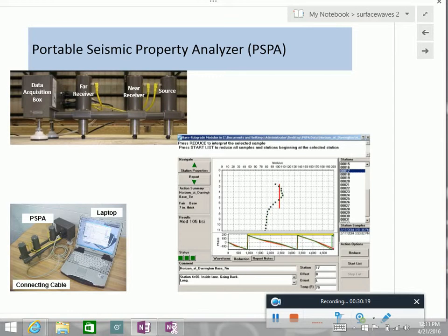But actually what I did when I went there, I said, no, why do we do that? This is complicated. Why don't we use these two as impact echo and plug in this velocity into that and get the thickness from impact echo? It's much better. And then bring the thickness back to get the average modulus.